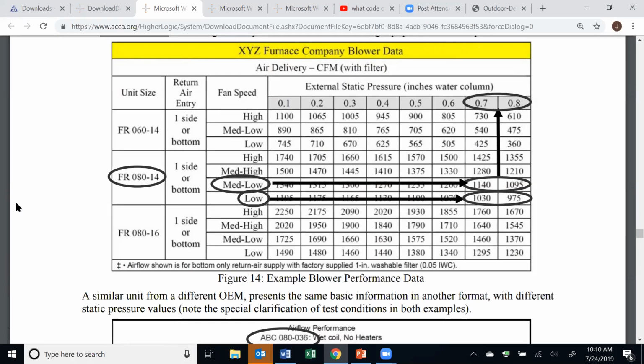By and large, the thing we're looking for is, was this considered? Did the HVAC contractor walk through this process when designing the HVAC system? If you're in a humid climate and you see airflows that exceed, say, 450 CFM per ton, that's a concern.